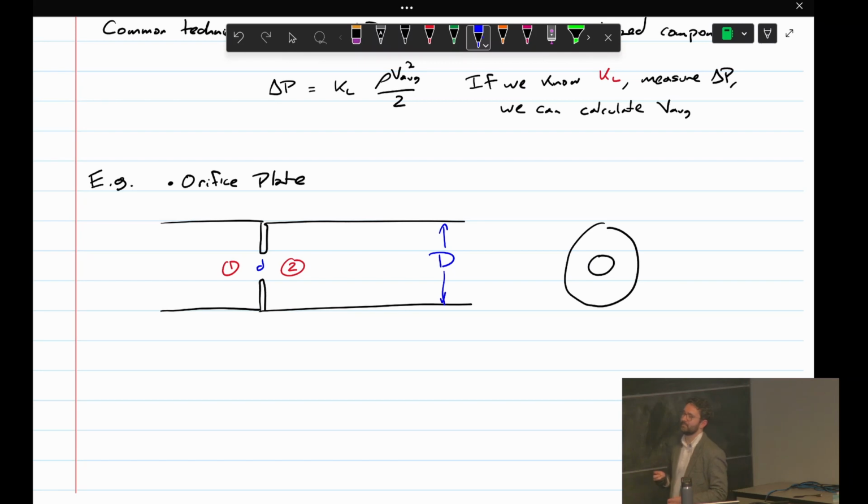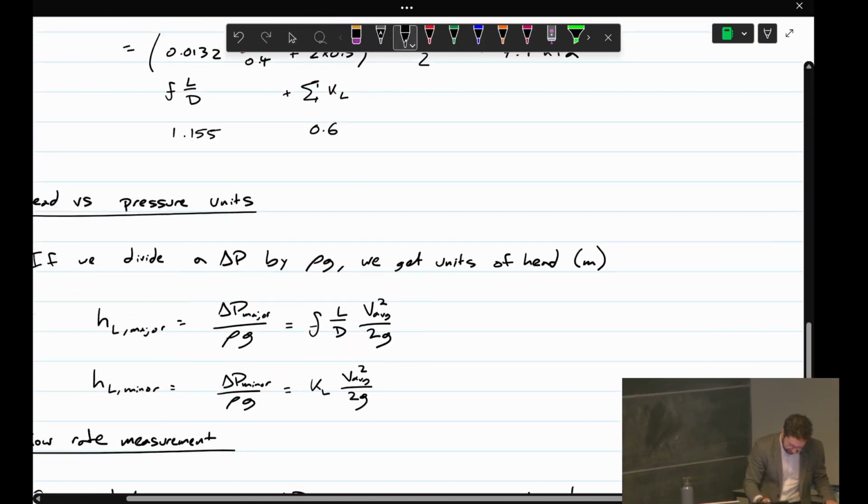This is different than the minor loss that I talked about. That pressure drop, delta P, is not the same delta P as the overall minor loss of this orifice plate. This is how the measurement works, because in practice it's pretty impractical to measure the pressure differential across that. So you can just put two pressure taps right beside each other on each side of this plate. The equation is a little bit different, but it's the same principle. So this is not the same thing as the unrecoverable minor loss.